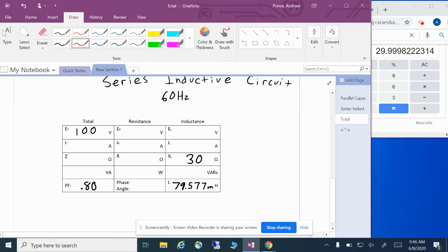Well, the answer is yes. You have your power factor there. And remember that power factor, even though we don't know what the power, true power and apparent power are, we know what the factor or what the ratio of those two was to each other. And in trig, that ratio is all that really matters. So the only reason we're dividing those two numbers is to get a ratio, which is that 0.8. So whatever those numbers were that we don't have, the total to that division problem would have been 0.80.